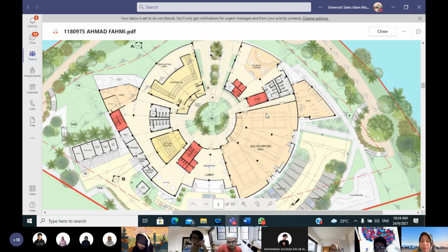But if your purpose group is for public, even though it is less than 12 meters height, you still need to provide another fire staircase, to allow the public to evacuate the building within the time specified for fire doors, meaning within 1 hour all the occupants in the building can evacuate. So you need to know how to place the fire staircase.